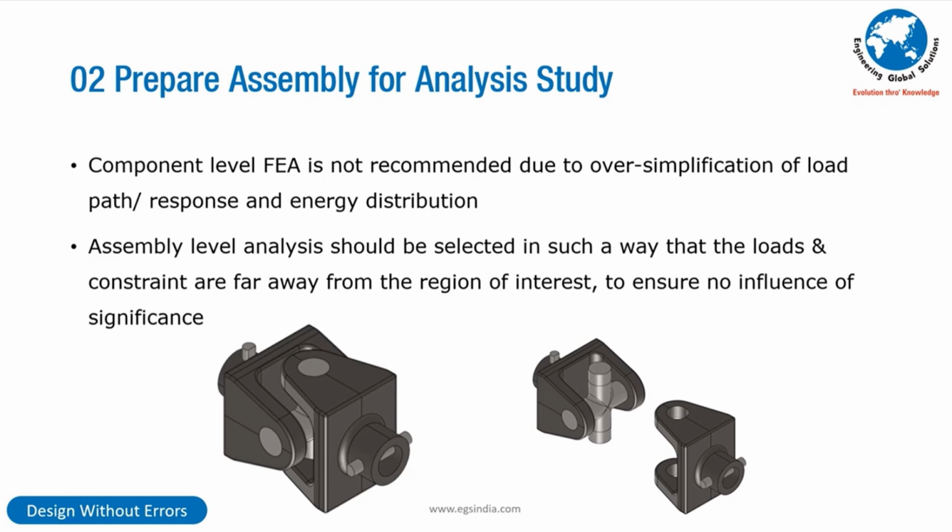So the assembly, for example, you look at the yoke here. This yoke has an upstream yoke, a downstream yoke, and a trunnion coming in between. If I am doing the durability calculations for the trunnion, I need to have the upstream yoke and the downstream yoke with the contact mechanics built in so that I can do the analysis in complete contact so that the energy is going into the entire system in which I look at the life calculations for the trunnion.